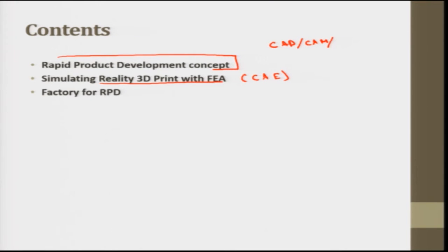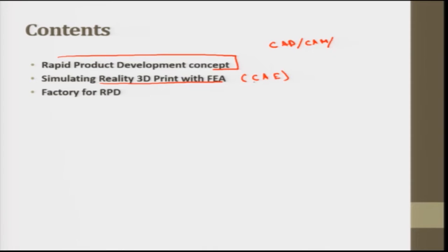The design that we make, taking the dimensions or scanning the object, we make a design. Then we need to analyze whether this design, if we select a specific material and the dimensions that we give, would bear the realistic conditions or not. Then certain analyses have to be done: stress analysis, thermal analysis, fluid dynamics. All those things can help to conduct an analysis that would make the product viable in a virtual environment. What is virtual and real environment, that we will discuss when we see the rapid product development scenario at first.